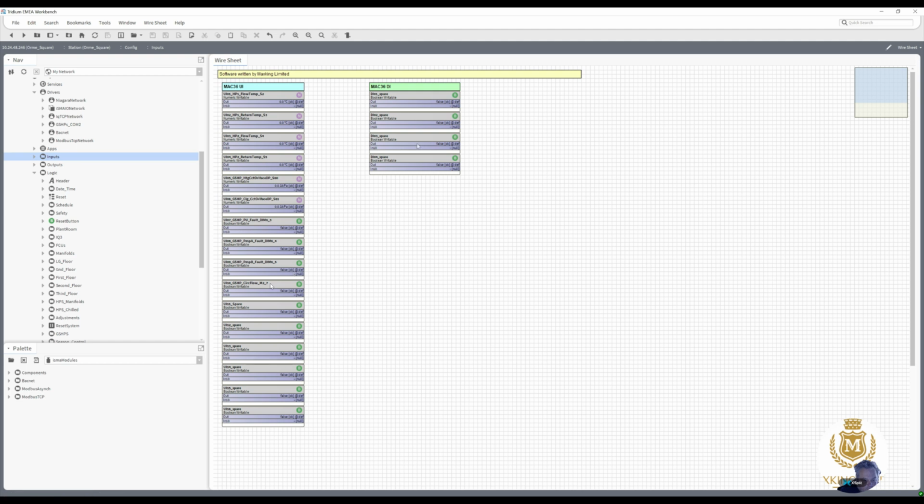I've left the MAC36 DIs because these can be used as pulse inputs for counters, and we may need that in future. So at least I can bring in 4 pulses into this module without having to buy another module. So there's no point in using them up for normal binary inputs. Might as well leave them spare so they can be used in future.